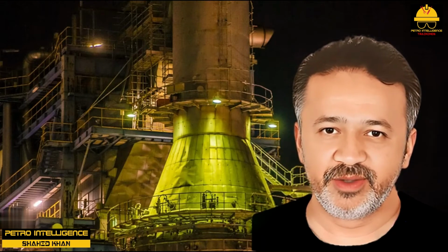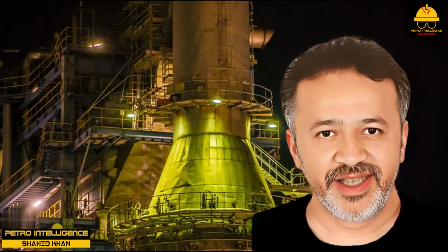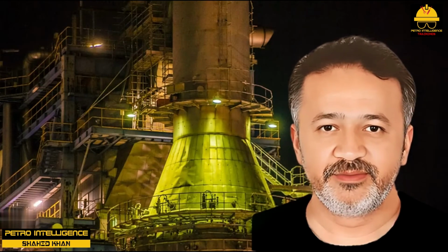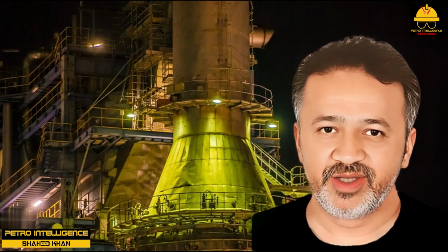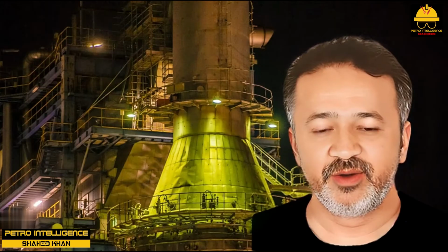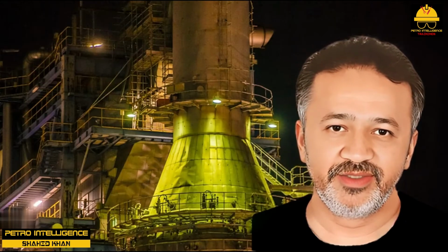If the firebox appears hazy and the flames are long, licking, yellow, and smoky looking, then there is not enough oxygen. To be just right, the firebox should have a very slight haze and all the flames should be compact and not searching around the firebox looking for oxygen.